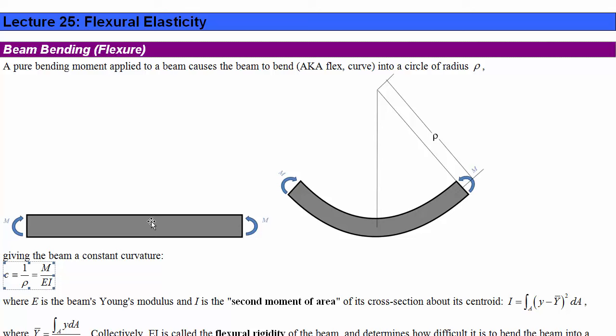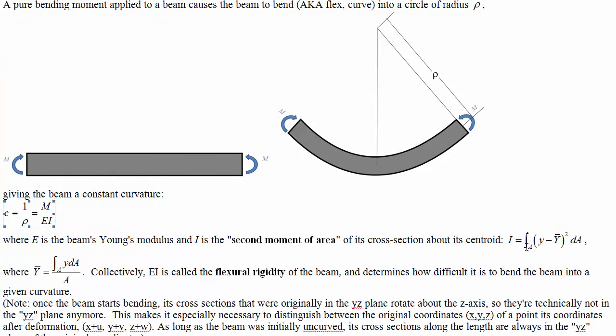So the cross sections are kind of slices through the beam like this. If you imagine one is in the vertical direction and the other dimension is into the page. Those are the two dimensions. So it's not this way. It's a cross section if we slice through the beam like that. And so the second moment of area about the bending axis of the cross section is, for a given cross section, the bending axis is in and out of the page.